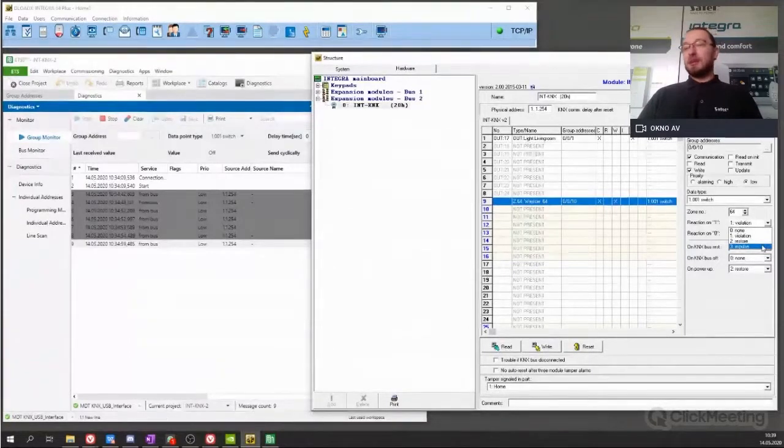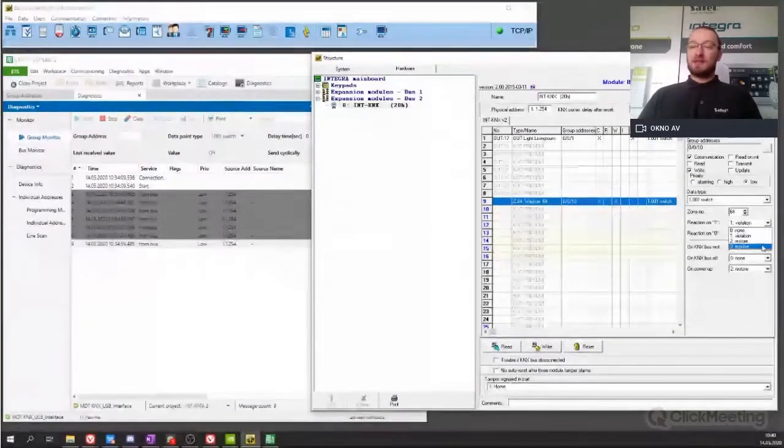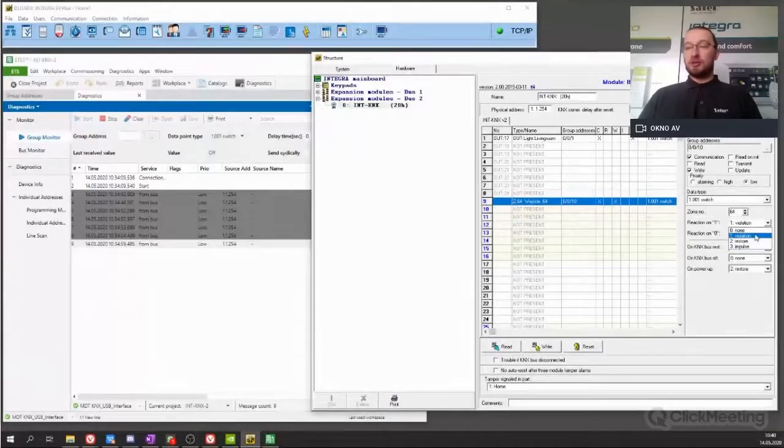In the INTEGRA panel, in security systems in general, an impulse is sometimes used more, like for example a PIR: if it sees movement, there is an impulse. If the status stays like this, there is no new alarm from this place. That's why we put an impulse, so that you don't need to send an additional 0 after it. So we will use violation and, of course, the reaction to 0 is restore, so going back to default.